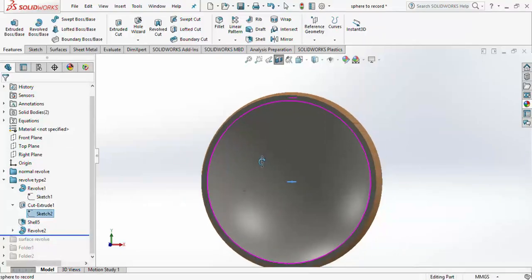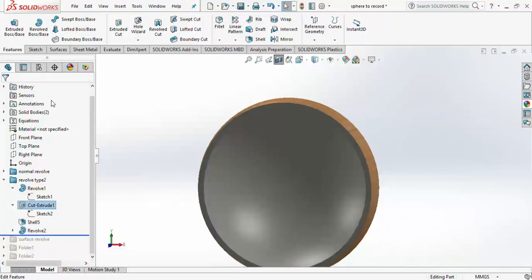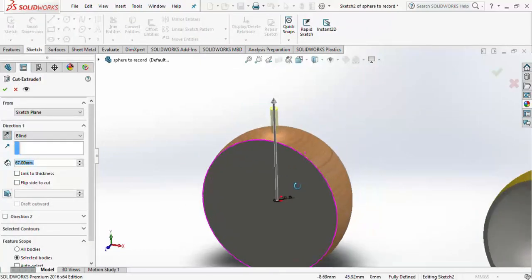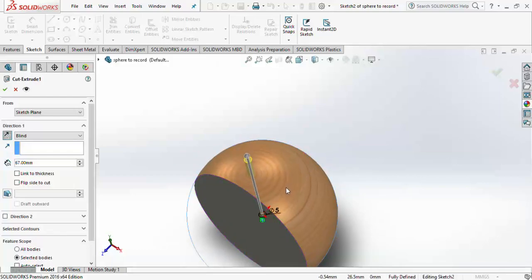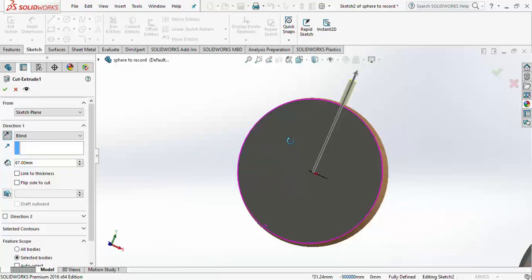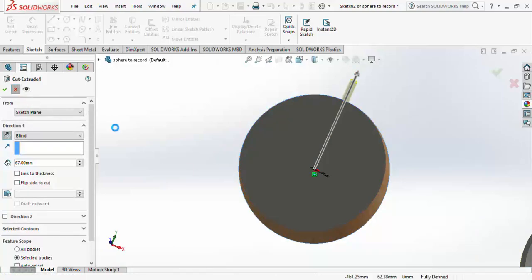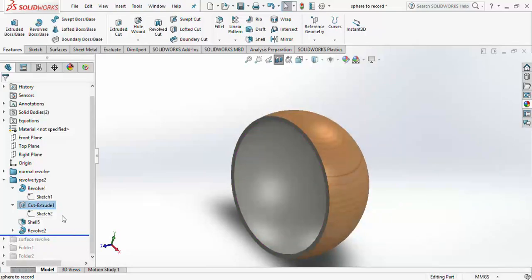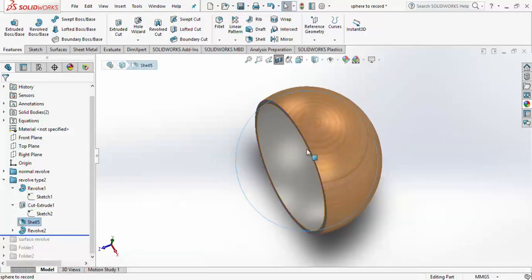If I show you what I mean, so it's got extrude. Basically, you take a plane, you draw a circle, you say cut it up to the end, one end, or either end, it doesn't matter at all. There is no difference unless you want to work less, because at the end of the day you could draw the top here, fill it up, and the bottom here just mirror it. So basically I did one side, and then I said, okay, I'm going to shell this.